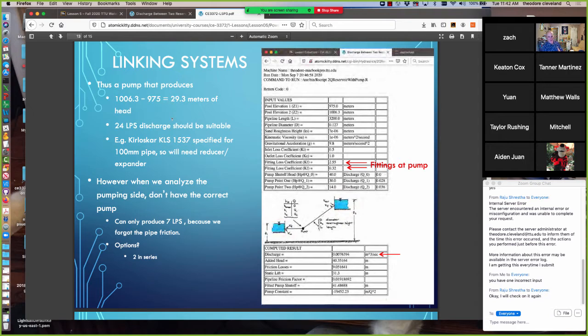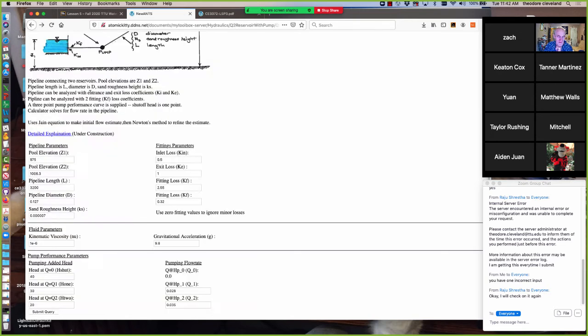So we have to make a choice. One is to go look for another pump. That's probably the smartest choice, but why take the smartest choice when I can look at some other one? A second one that's worth examining, even though you may never buy it and build it: what would 2 pumps in series do? If you recall, and you'll relearn next time again, 2 pumps in series can add head. At the same flow rate, they add head.